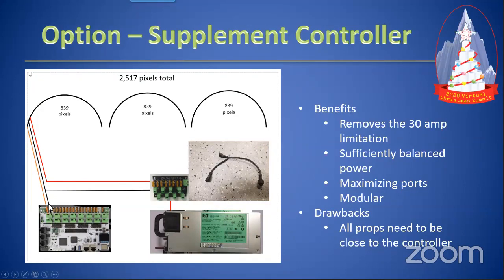In that example you have up, if the power supply is powering the controller, can you just send the ground and the power from the distro board and just a signal from the controller? You still want the ground. Yes, you still want the ground, and yes, you can. Okay, thank you.